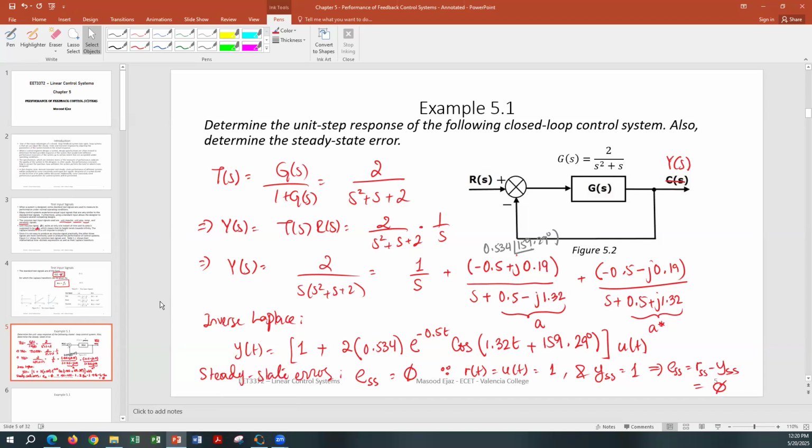Before I do that, let me ask you a question. If you are plotting this, how long are you going to plot the response against time, and what step size do you think you will be taking? That will be not 0.5, but 1 over 0.5, that's the time constant. So how many time constants? You said 5 approximately. Okay, 4 to 5 time constants.